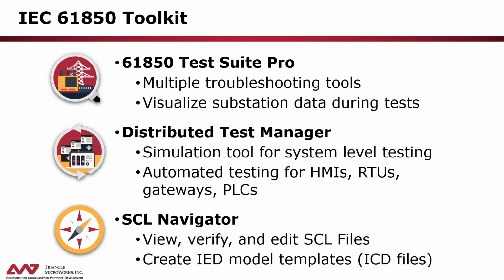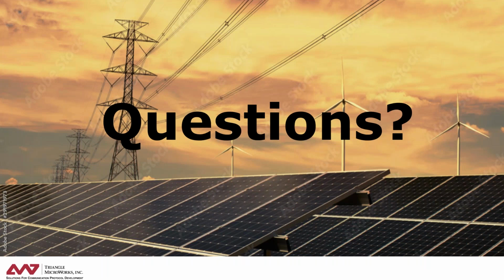Distributed Test Manager is our system simulation tool. It can simulate not only 61850 devices, but all the other protocols we do, DNP, 870, Modbus, TASE.2. With 61850, we'll import the SCL file and be able to generate a simulation from that. And we also have SCL Navigator. We won't look at that today, but that's an ICD editor and SCL verification tool. So I think we've gone through a couple of rounds of questions. We're going to go on into the quick overview of the tools here.